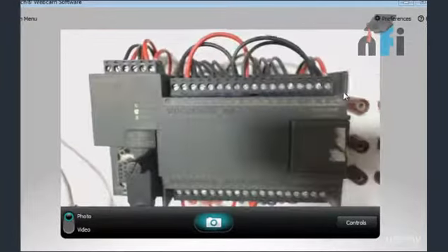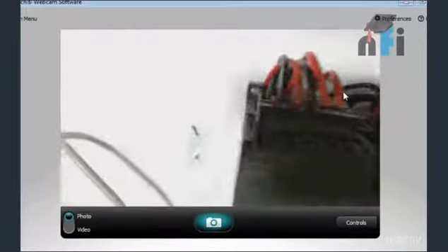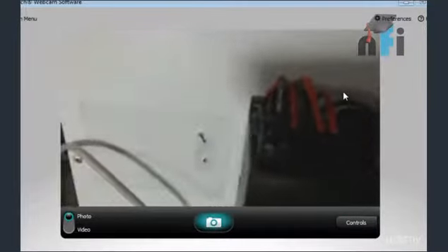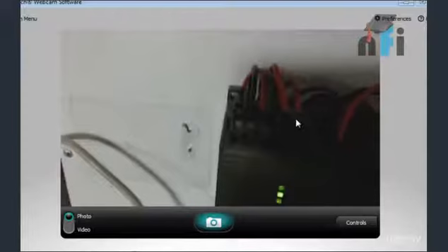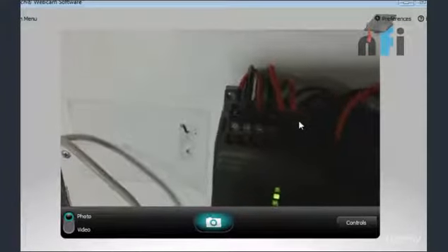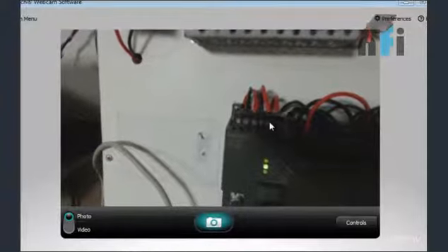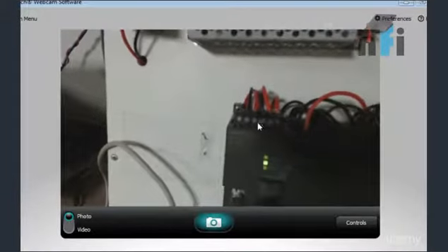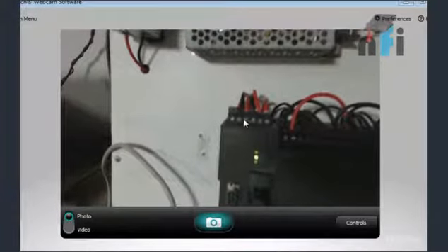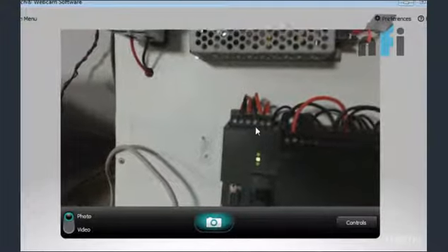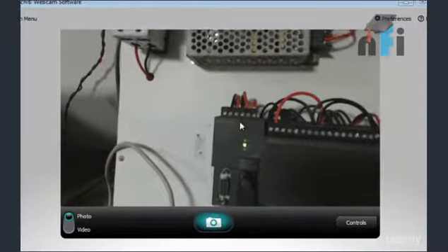And over here, if you see the top part of this, this is the analog input and output of the PLC. You can see that it's a little dark here. This is A plus, these two are analog input, this is the common, and these two are the voltage input and current input of this PLC. So this is the analog input output part, we'll see that later on.